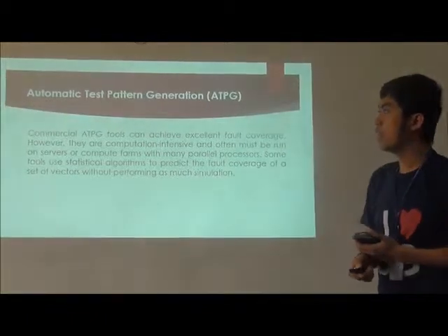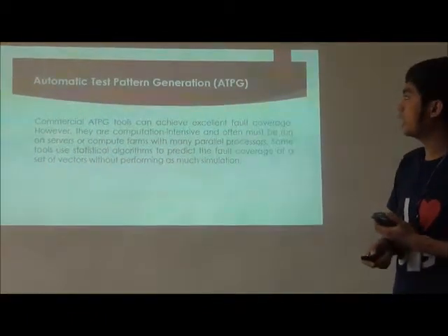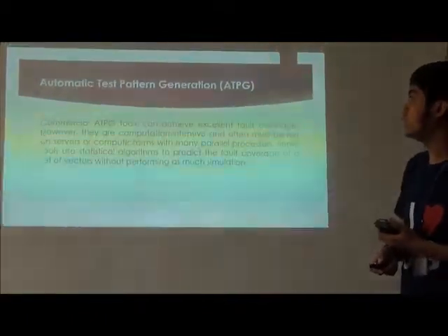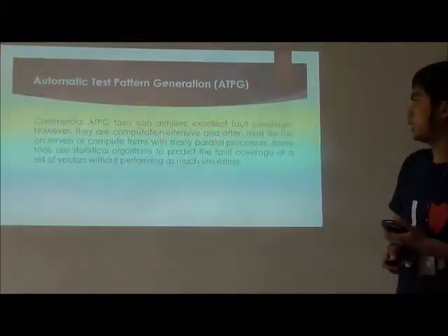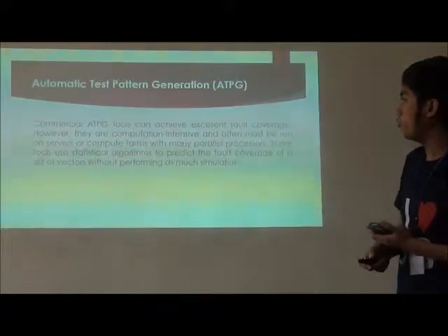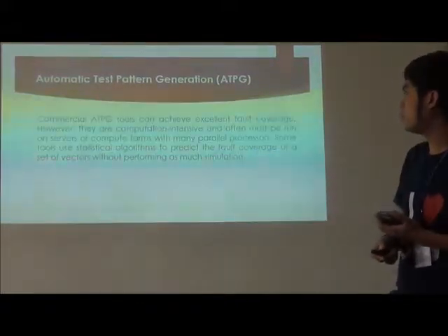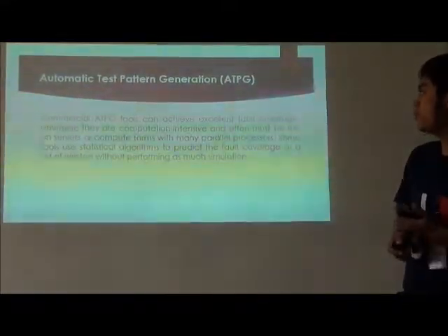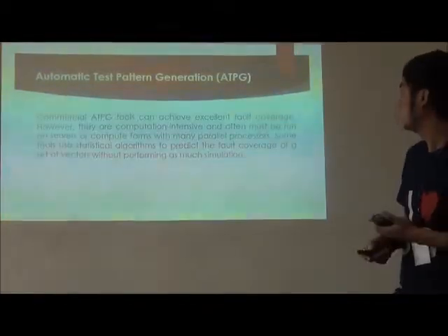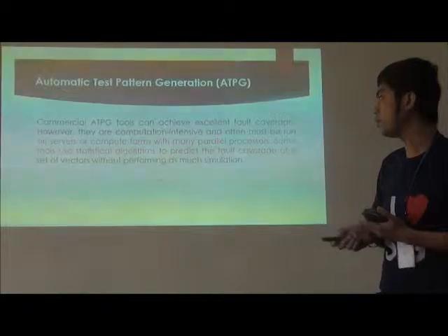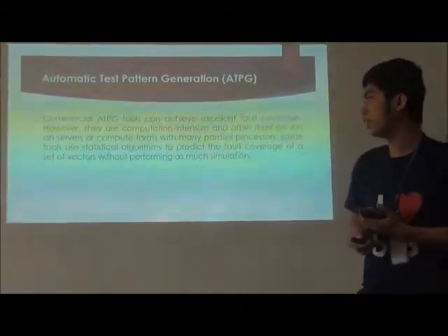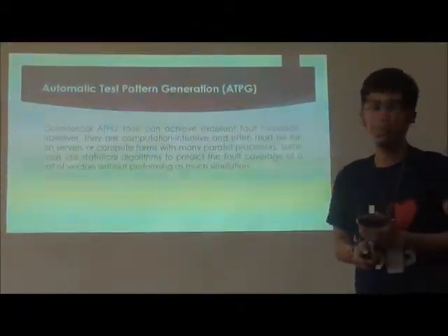The next part is automatic test pattern generation, or ATPG. Commercial ATPG tools can achieve excellent fault coverage. However, they are computation intensive and often must be run on servers with many parallel processors. Some tools use statistical algorithms to predict the fault coverage of a set of vectors without requiring as much simulation.